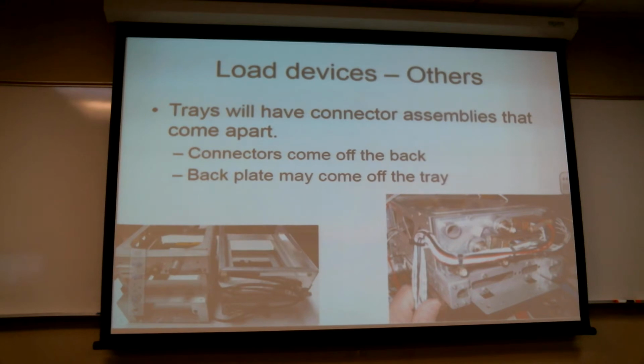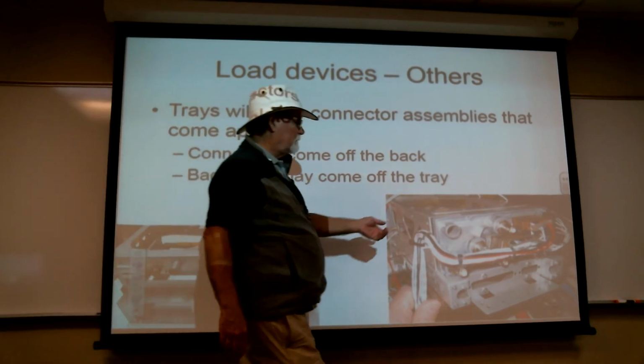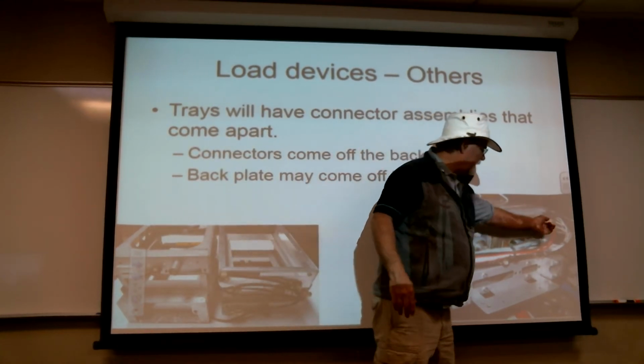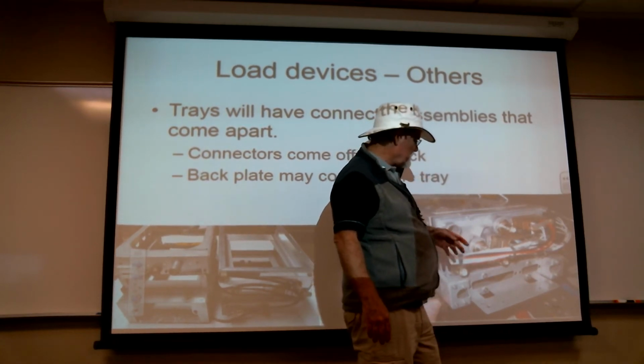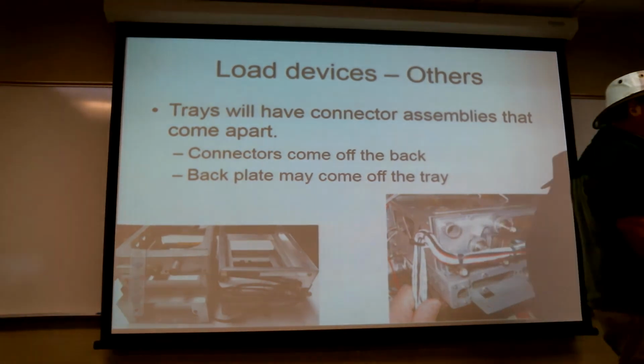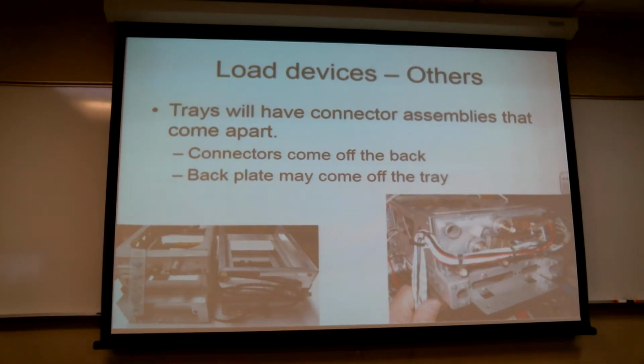Whereas if you look at the Garmin assembly, I know that's a Garmin right there, that plate, it's got a fitting for cooling, but the antennas come out straight, as do the coaxial connectors. So in this case, if this unit is, say, 12 inches deep, I'm going to need another 3 inches or so behind there to be able to pull these cables out and gently make a turn. These are not so bad because I can turn them tighter. That hose is going to need a little bit of a gentle turn. And again, all the coaxials will need a little bit more of a gentle turn as well.